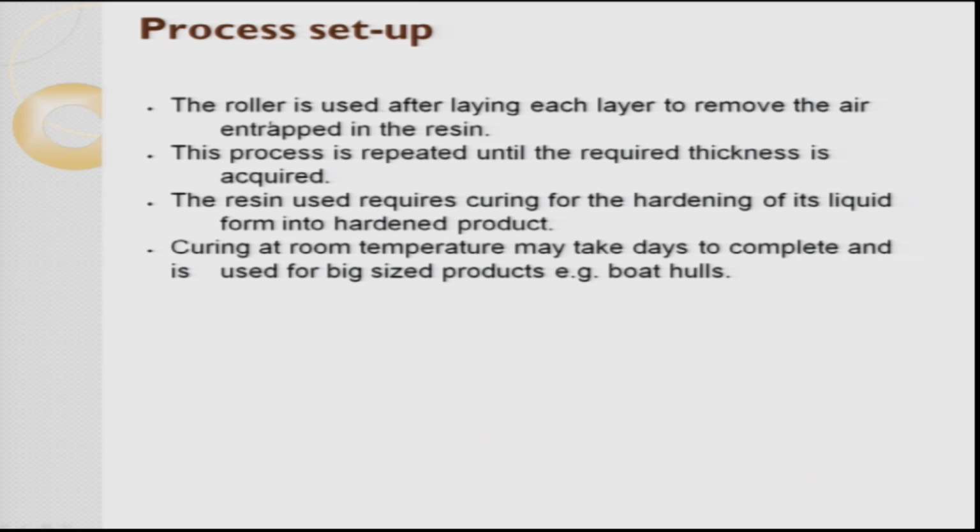The roller is used after laying each layer to remove the air trapped in the resin, and it also removes the excess resin. Generally, excess resin means you will have certain pockets where there will be more resin. When more resin is added, the part becomes heavy.